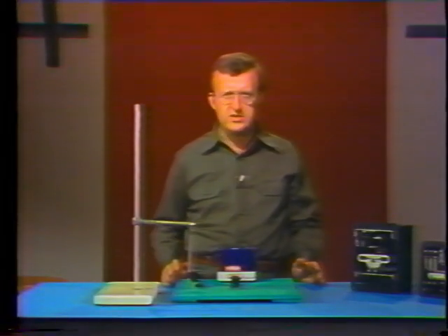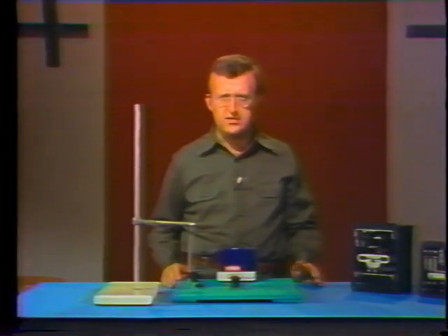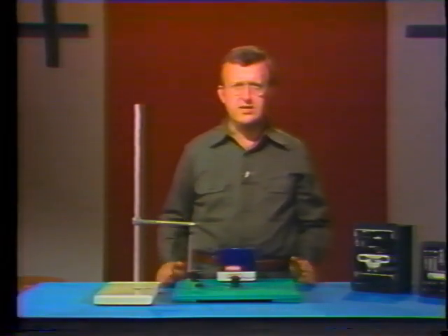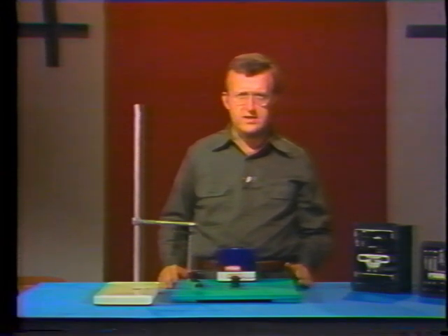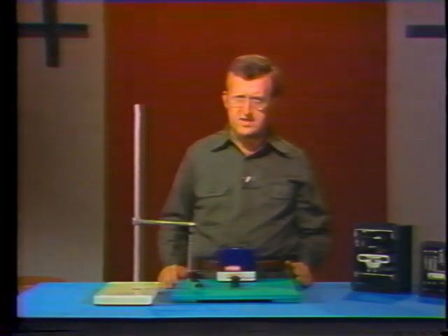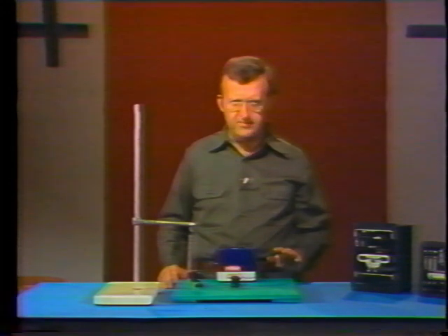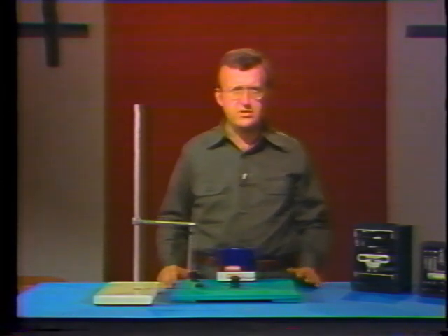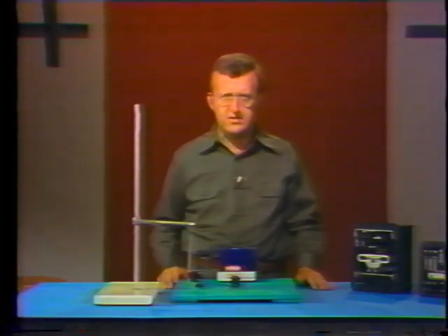The example we just saw is one way that solenoids are commonly used to control valves. Solenoids can also be constructed so that they cause a valve to close when a solenoid is energized. With this arrangement, de-energizing the solenoid allows the valve to open. Designers must examine each application to determine whether a solenoid valve should open or close when it is energized. The main consideration is making sure systems are kept safe if there is an accidental loss of power. Solenoids are also found in applications other than opening and closing valves.